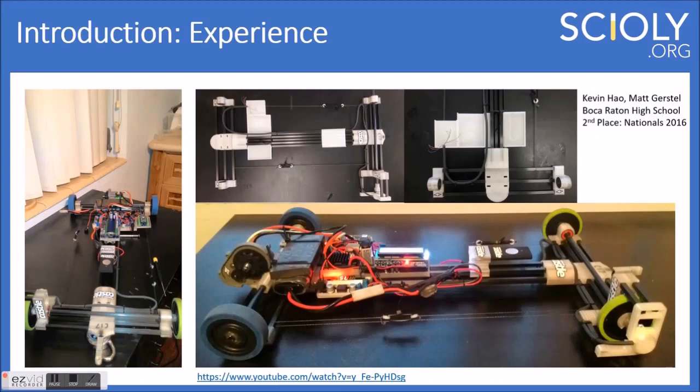So we really found the need to separate these functions to separate microcontrollers just because we didn't have enough processing speed on one. And if we tried to run everything on one, it would start to miss clicks and stuff, and then we wouldn't have the right distances, which is a huge problem.